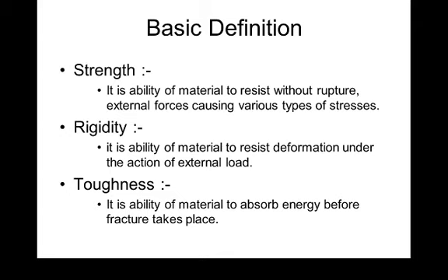For ductile material the demarcation line between yield strength and ultimate strength is available. For ductile material, whatever stresses develop should be below the yield limit, provided that the forces are static. If the forces are fluctuating loads, then the component will fail below the yield limit, and that limit is called the endurance limit.